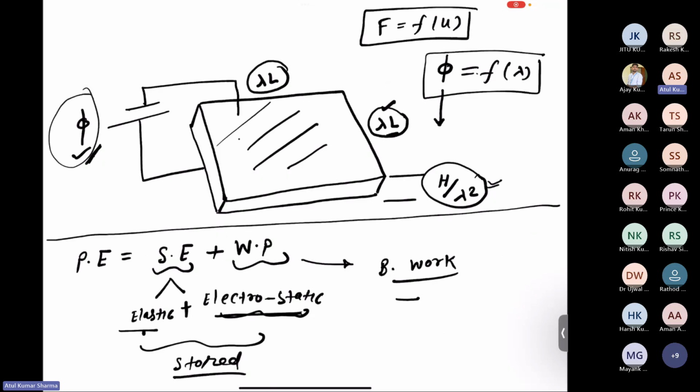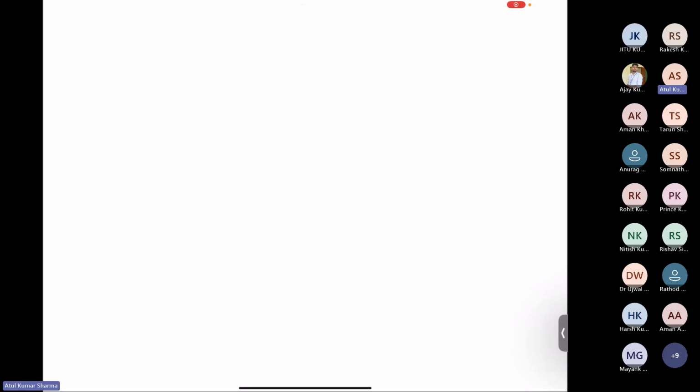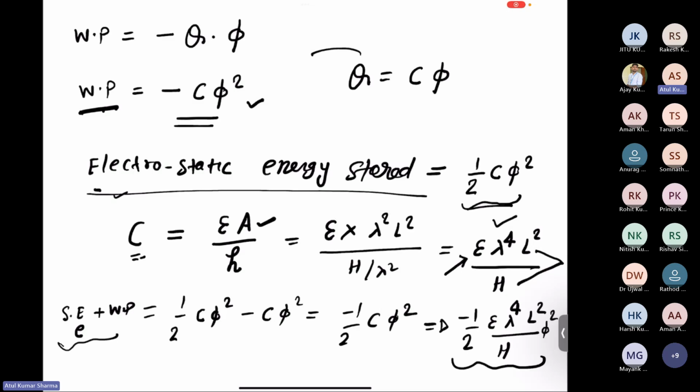Now one quantity remaining is the elastic part of the strain energy. For this kind of material, which is a rubber-like material, in order to model the rubber we use a hyperelastic material model. I will be considering a simple case, which is the Neo-Hookean material model.